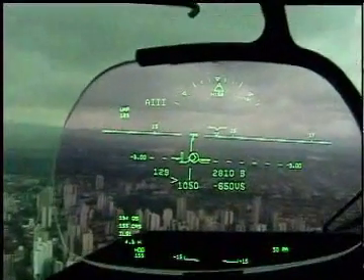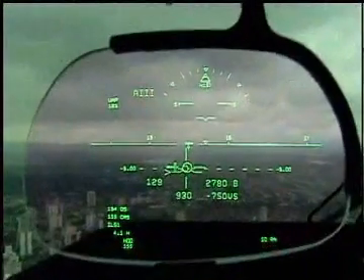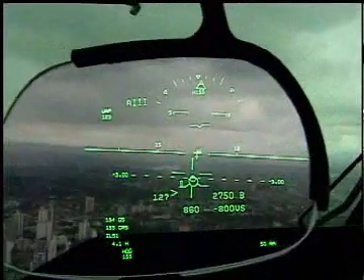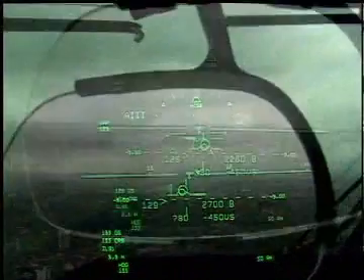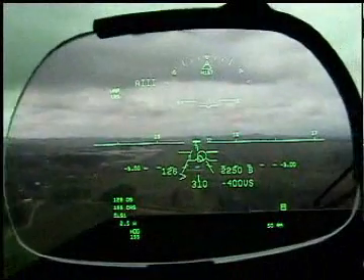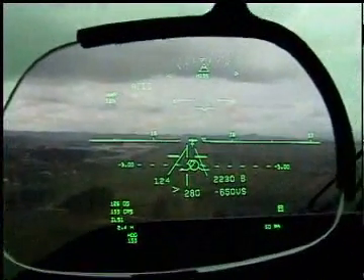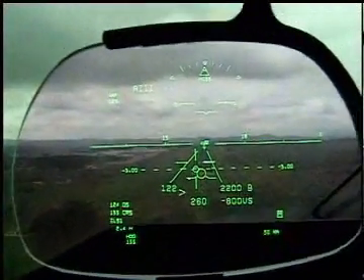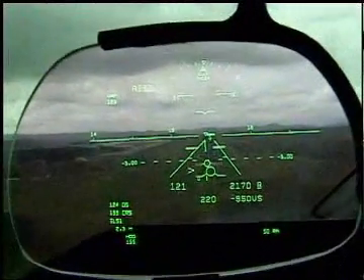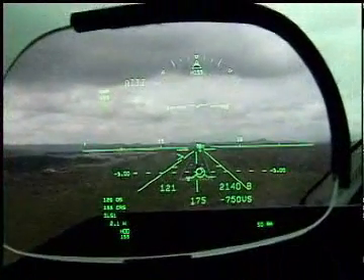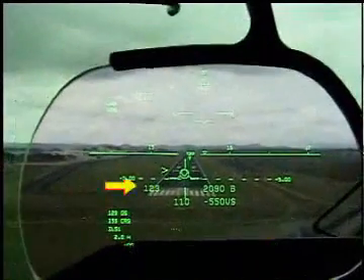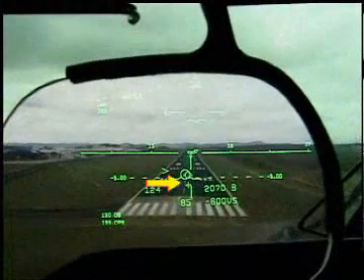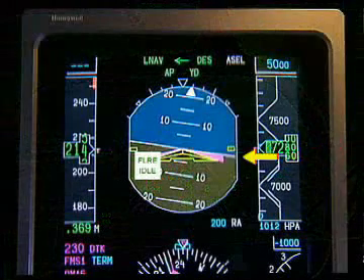The A3 annunciation displayed in the upper left corner is both an indication of the selected mode and the HGS capability of providing guidance. As long as all required parameters and conditions are valid for a Cat 3A approach, the A3 status annunciation will be displayed. Flare initiation is indicated by the flare command on the combiner display and the flare annunciation on the PFD.